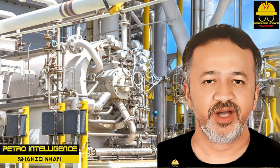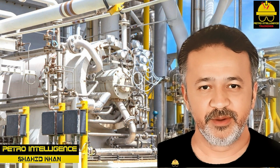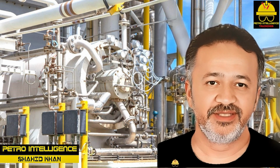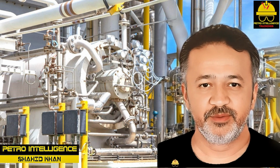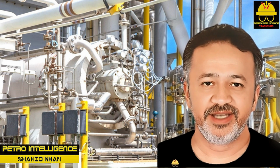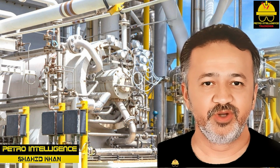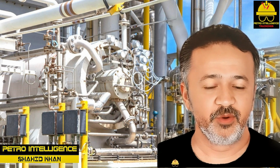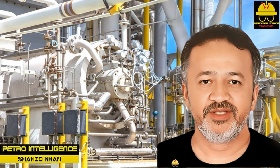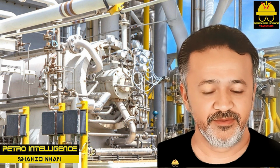Positive displacement compressors. Positive displacement compressors operate by trapping a specific amount of gas and forcing it into a smaller volume. They are classified as either rotary or reciprocating. Rotary compressors are further classified as rotary screw, sliding vane, lobe, or liquid ring. Reciprocating compressors are classified as piston or diaphragm.